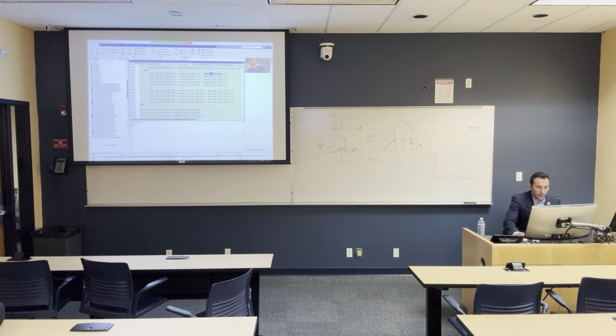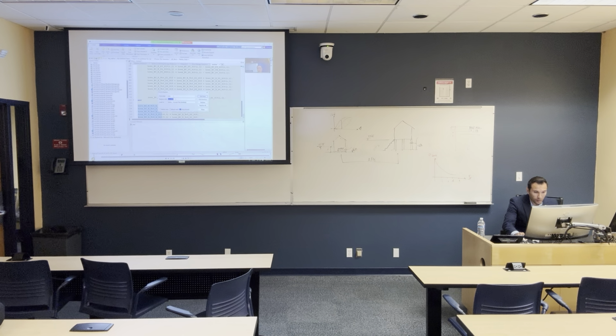Okay? And once I'm done, I'm writing all the flood loss reduction outside in this matrix. And then I'm going to the 20%. And I told you, in this case, all you have to change is just one thing. You go back to the folder that you have here, and if this one is right and it has all the elevated components, you take this copy, Control C, Control F, and change from S10 to S20, and then replace all.